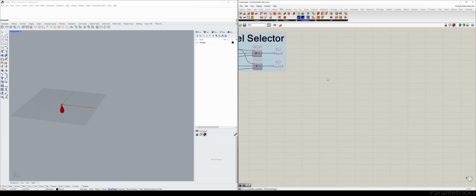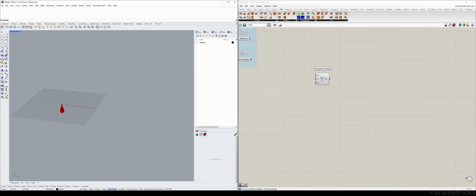So to start, what I tend to do is make a point. So I'm just going to make a point construction. First off, I want to dictate how high I want the strings to start, like from which height they drop from. And then from there, I can do a multiplication in the x axis and then the y-axis, and then I also have those two as sliders so that you can control how many droplets we want.